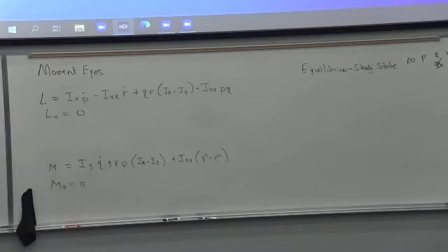The steady state flight condition is like that. And you look at that and you go, okay, the sum of the moments is 0, that's pitch trim, right? So that makes sense. This is a steady state trim condition. This is pitch trim, this is roll trim. So that makes total sense.